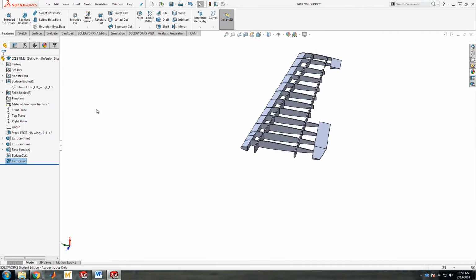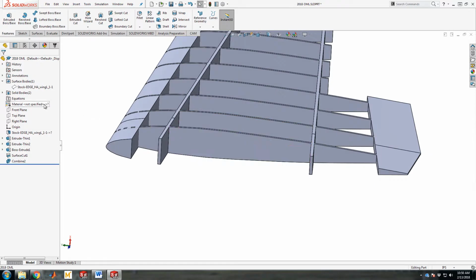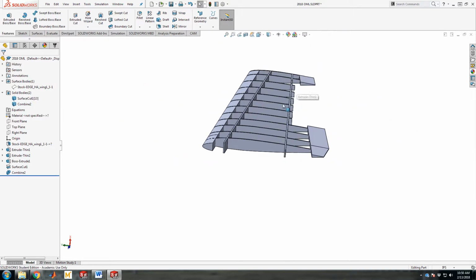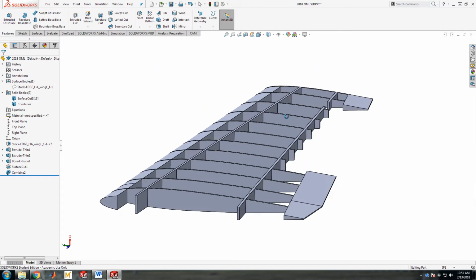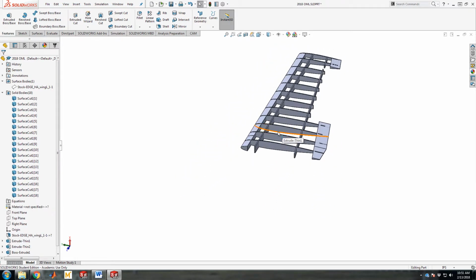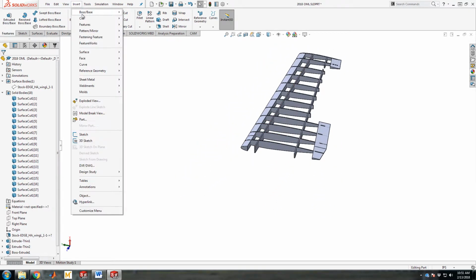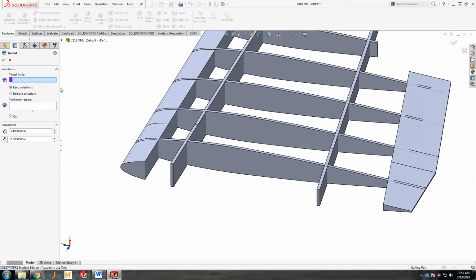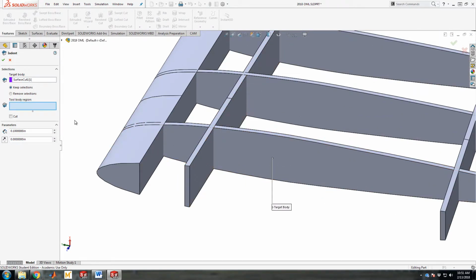Click OK. It does some maths, and now you have 2 bodies remaining. You just have the leading edge, and you have the rest of them. So you can use Boolean operations to combine multi-body parts relatively easily as well. Undo, all separate. OK. Insert features. Indent is actually more useful for a lot of aerospace applications and part making than cut, which is kind of weird. The target body here I want is, again, the rib. The tool body will be the spar. I want to remove the selections. It'll be a cut. Okay, so it's giving me a preview. I think that's right.